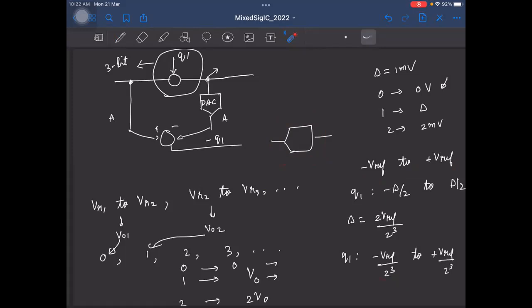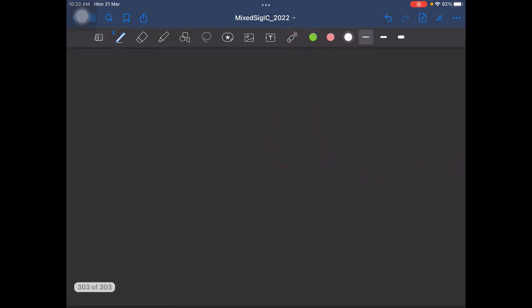If you directly feed it in, this range might not even cross one of the threshold levels of the second ADC. That is, quantization noise might be here, and you might get a constant output at the second ADC. Only if the input spans this entire range will you get all the codes, from all zeros to all ones.